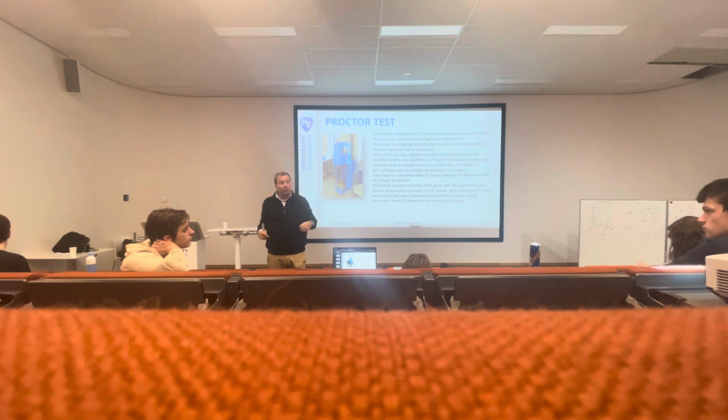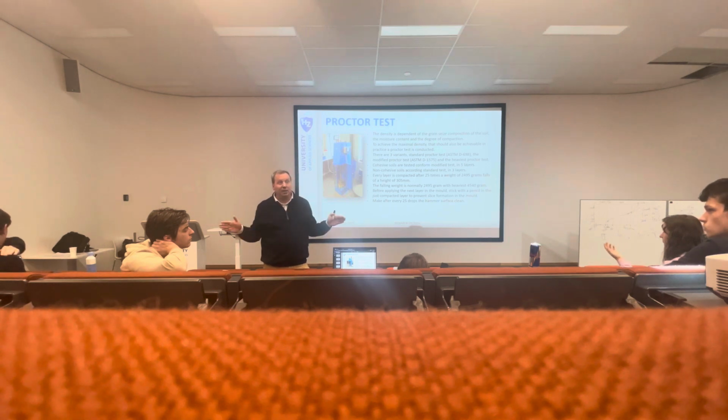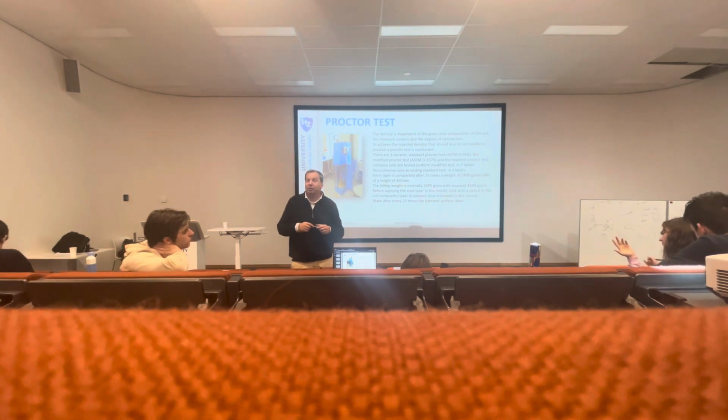When you were playing at the sea or at the beach or at the lake in the past and you built a castle with sand, if you added a little bit too much water, it fell apart, and when it's too dry, it doesn't work either. With clay, due to the plasticity of it, we have, let's say, a bigger range. You can be between 12 and 20, and still you get optimum compaction.